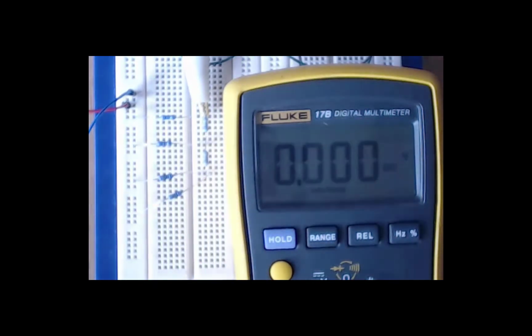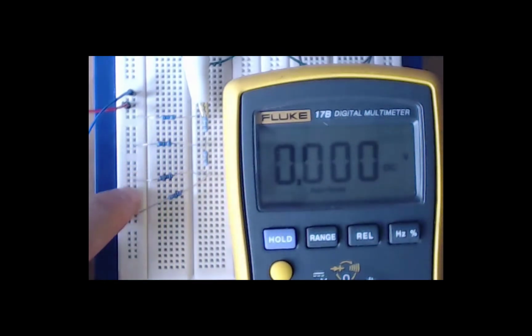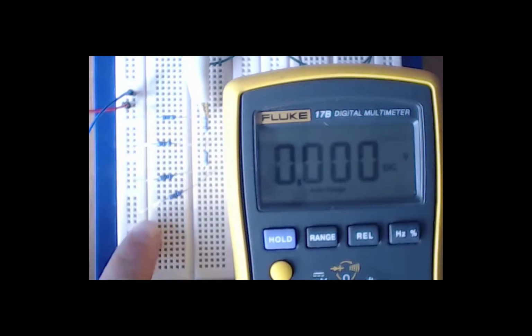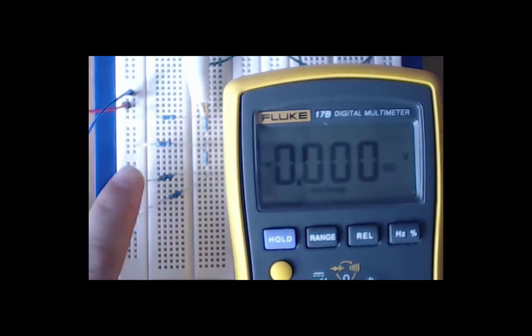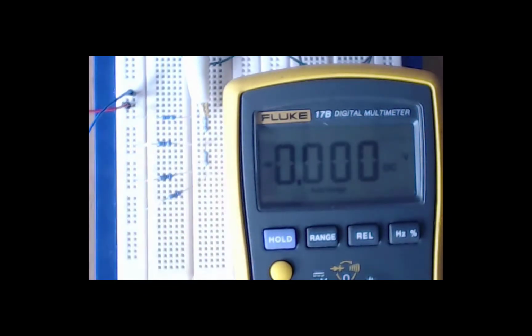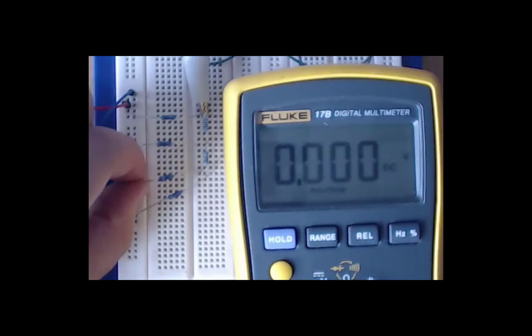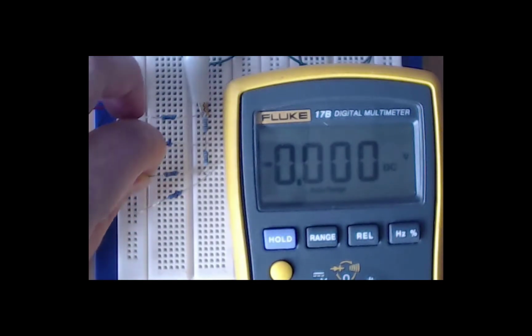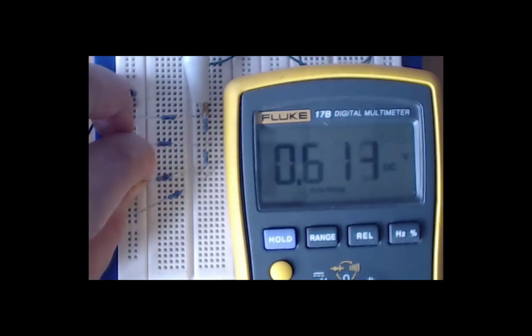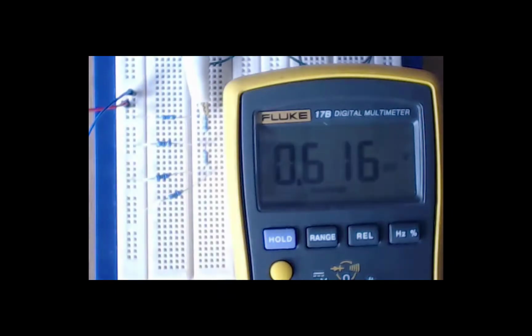We can very easily adjust by putting the resistor in either this slot or this slot, whether it's 0 volts, connected to ground like these ones all are, or in the next slot, connected to 5 volts, which is our VREF value. If we move our least significant bit from ground through to our VREF value, it gives us 0.616 volts output. Nice analog output voltage.